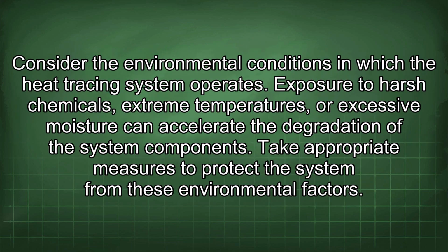Consider the environmental conditions in which the heat tracing system operates. Exposure to harsh chemicals, extreme temperatures, or excessive moisture can accelerate the degradation of the system components. Take appropriate measures to protect the system from these environmental factors.